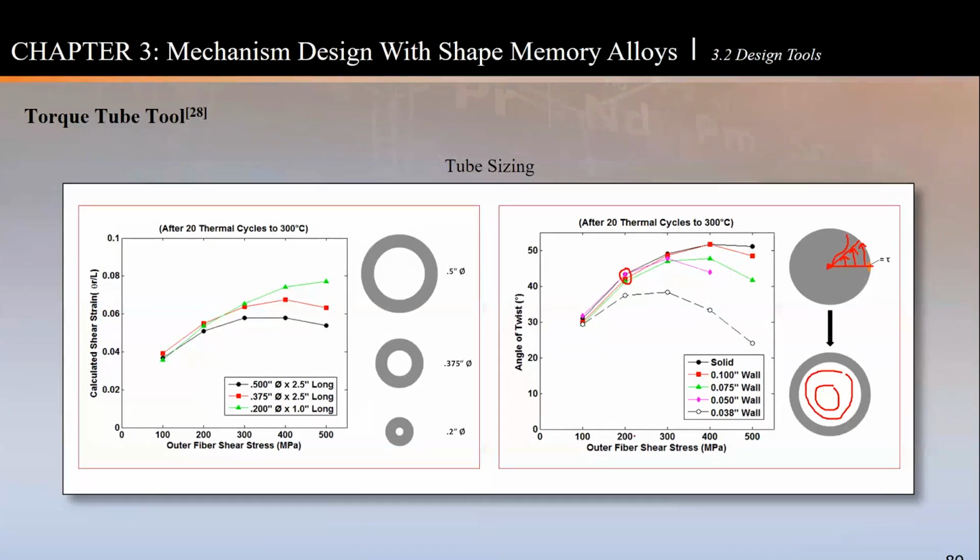In the normalized, if you plot it as load, obviously it's going to be different. According to the shear stress, it is the load times the radius divided by J. Okay. So that's okay, and then one last related question to the tube, the torsional tube. So yes. To create a torsional tube, you have to form your tube and then set it in a twist fashion at 500 C and set it, and then you've got your torsional tube.